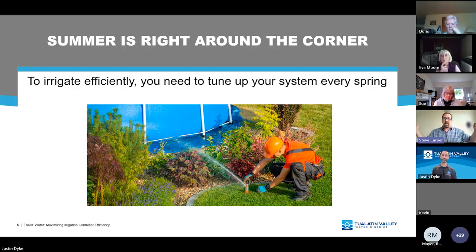Water should basically be spraying uniformly out of the sprinkler heads in a nice pattern, hopefully. But if you see things percolating up from the soil, then there's your cue to start digging once the zone is off. And generally, once you start disturbing the soil where that is happening, the water will assist in that excavation effort and make it pretty clear where the issue is in pretty short order.